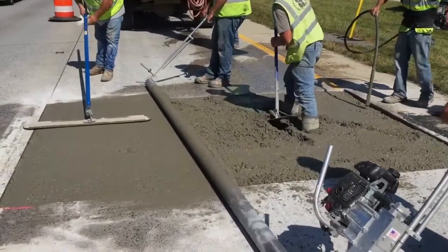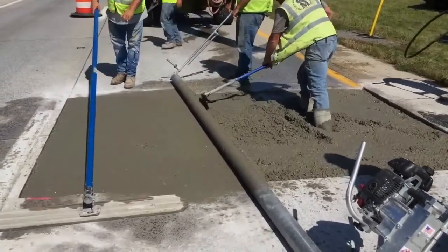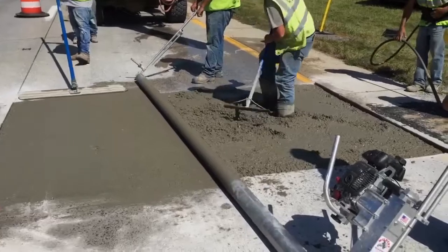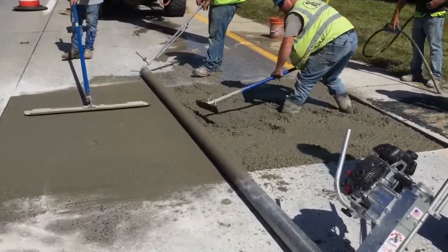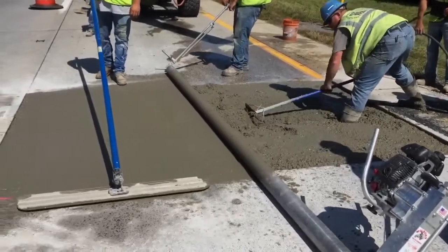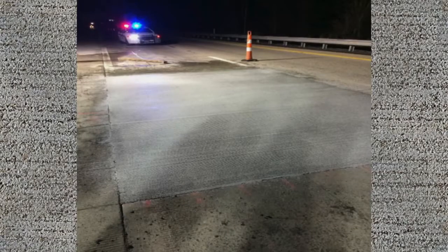Final finish of the concrete. For Type A and B patches, finish the surface of the patch to match the existing pavement, including existing wheel ruts. If the contract includes diamond grinding, the matching of the wheel ruts is not necessary. For Type C patches, taper the wheel ruts at both ends of the patch to a straight pavement cross slope within the patch, with a minimum transition length of 20 feet.